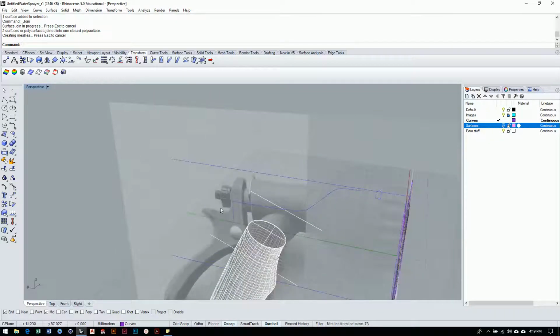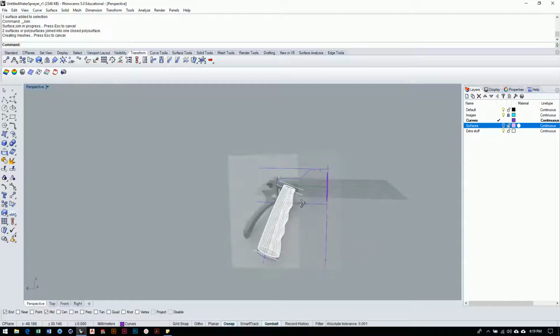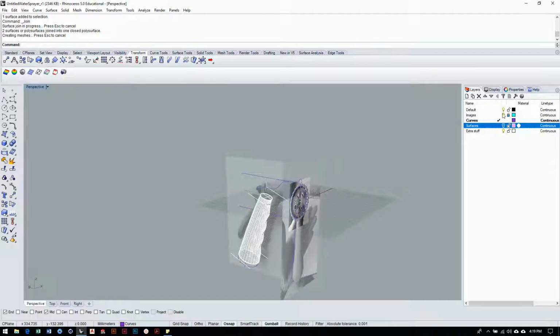That's all grouped now, and so it's a solid. Once everything is enclosed, watertight, grouped together, then you have a solid in Rhino. So now we can start using the solid modeling tools, like the Boolean union tool, which is what we're going to use next. So I'll turn off my curves, and we're just going to look at this extra stuff layer that I have here.